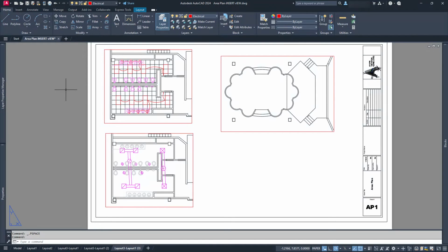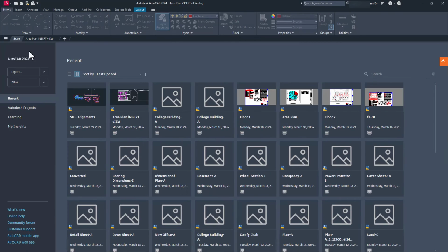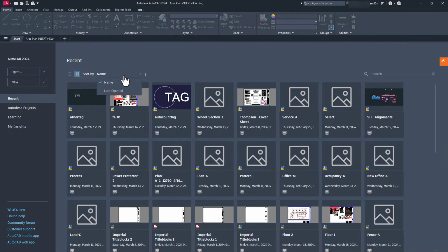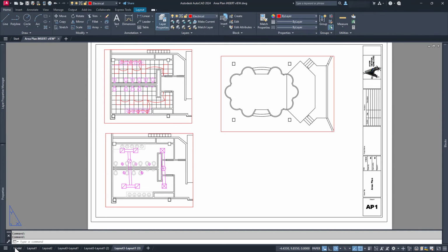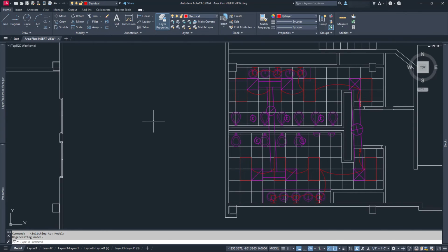While AutoCAD has new features every year, really meaningful changes are less frequent. 2024 added the ability to sort your recent documents in the Start tab. And while I do personally like the new trim command, I was even happier to learn I can go back to the old version by choosing the mode option in the command line and going back to standard when I need to.